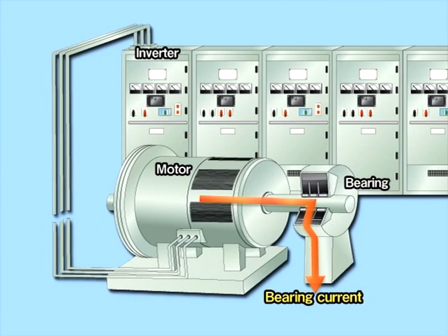It may be difficult to deal with this problem on board. Nevertheless, please keep the following in mind. Motors controlling the speed of winches and cargo pumps by inverter may have shorter useful lives. A filter circuit can be installed to prevent common mode noise.